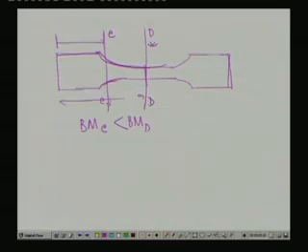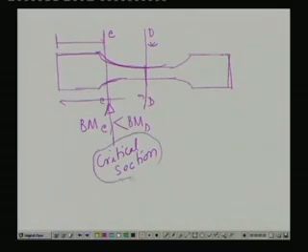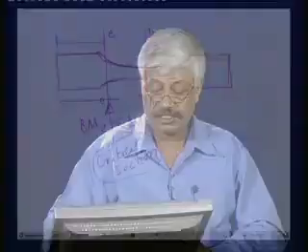Thereby, with the introduction of the fatigue stress concentration factor in the equation just discussed a few minutes back, we can expect that this C could be a critical section. Let us consider this to be the critical section with the logic we have just discussed and carry on our design.